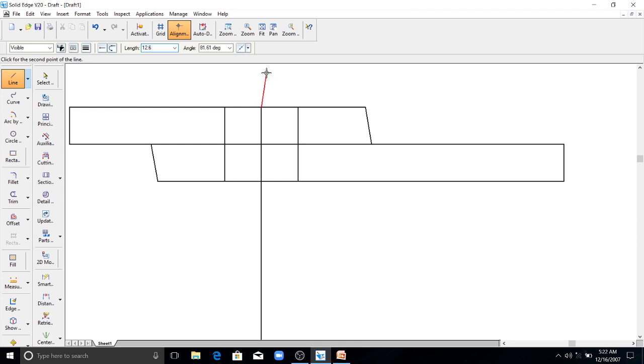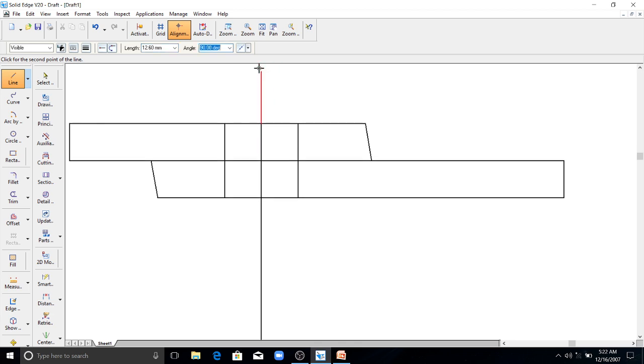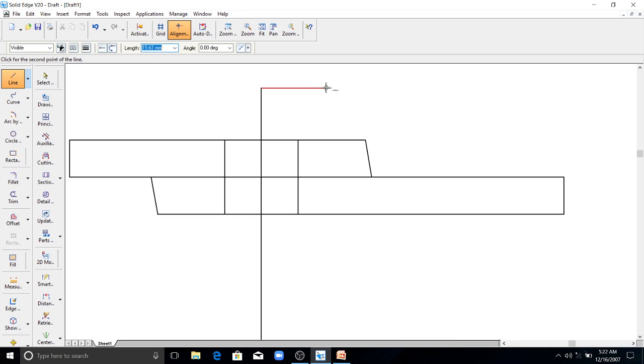12.6 mm, you draw a line here. Then this length, you have to take 0.8 D. So this is the half portion of the snap head. The 0.8 D will become 14.4 mm. You draw 14.4 mm here. You draw close. Now you have to draw the bisector for this and this. For drawing the radius of the snap head, you have to take the bisector of this line.